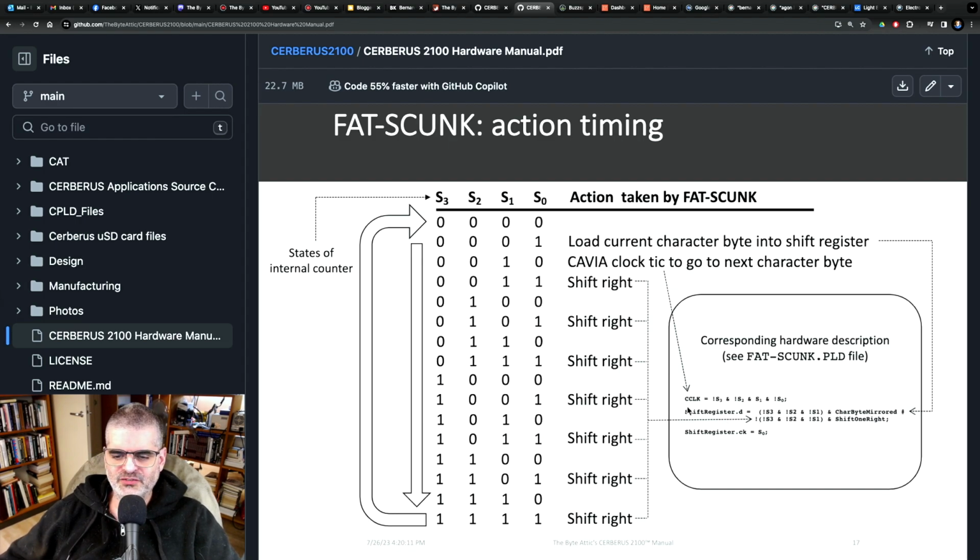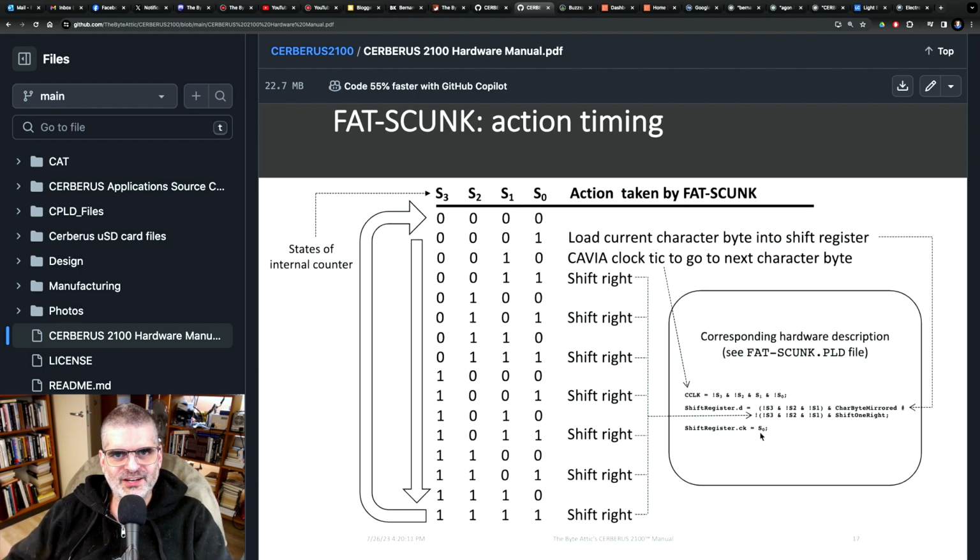Here we are using text instead of complex schematics which look like noodle soup and you have to follow the wires. Well, here you don't have to follow the wires. Here you just look at the names of the signals and you don't have to draw gates. You just look at the exclamation mark, an ampersand, and a hash for an OR, and an equal for an assignment. In other words, for a connection between two wires.